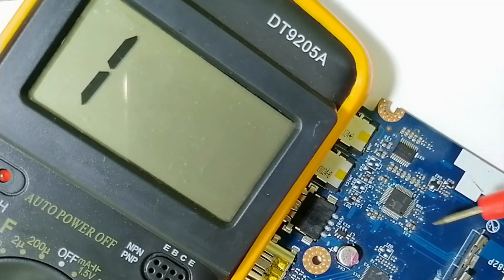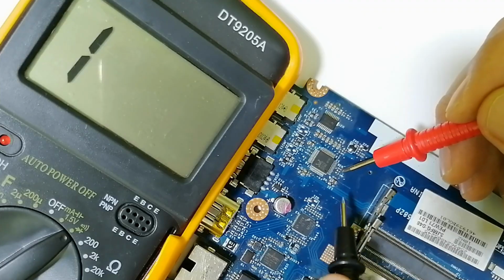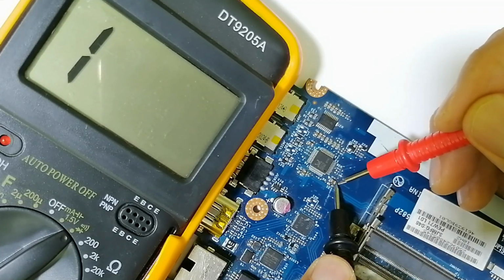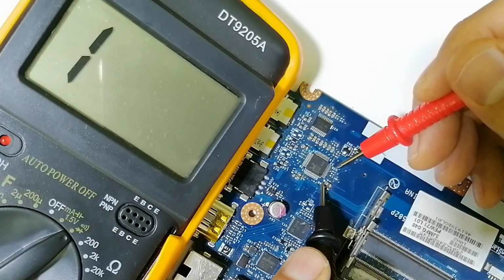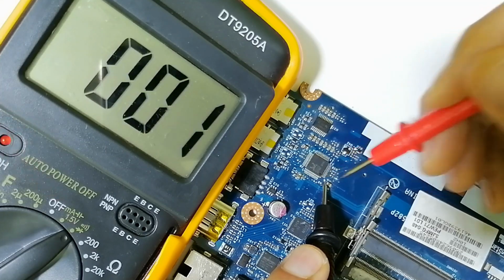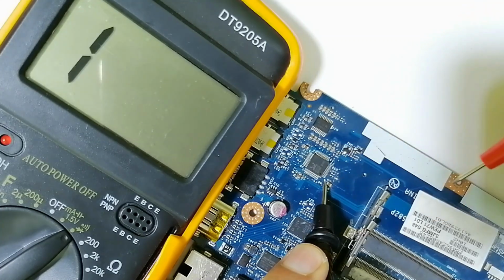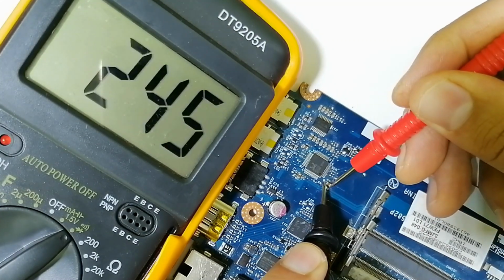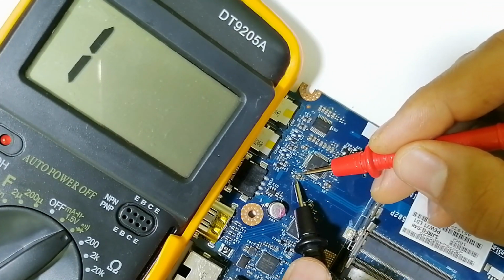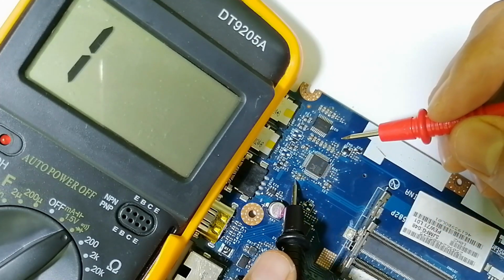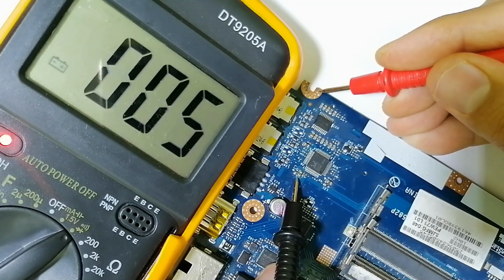Okay, so for the ceramic capacitors around every IC, you will find that the terminal of the ceramic capacitor in one side is connected to the ground, as you can see, and in the other side connected to the IC. But if you find this capacitor is shorted, it means the IC is shorted to the ground. Let's check this one. For example, it's not shorted, it means the IC is good. Let's check this one. Also, it's not shorted, but this capacitor always is connected to the ground in one side. Do you see?